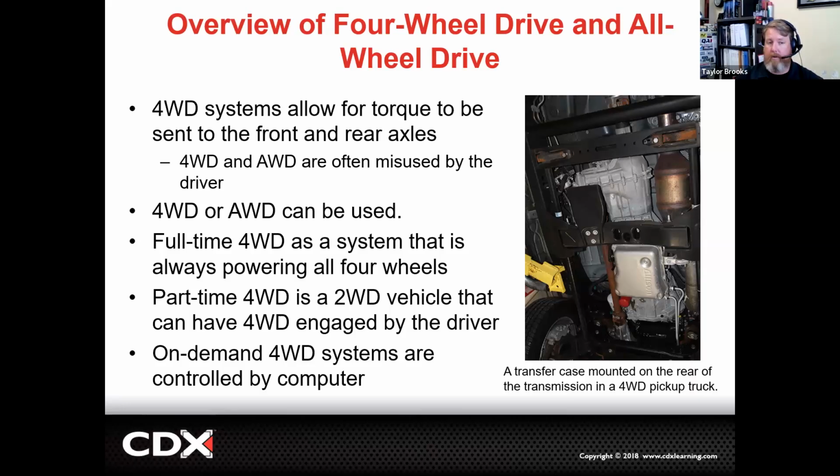Part-time four-wheel drive is what probably most of you are familiar with seeing in Jeeps and off-road vehicles. Part-time four-wheel drive indicates that part of the time you can drive the vehicle in two-wheel drive, or you can select it to drive in four-wheel drive, depending on the road conditions. In most driving applications, in fact, about 98% of the time, the vehicle is going to be driven in two-wheel drive or just rear-wheel drive mode only. And then when we select four-wheel drive, either high or low, it will then send torque to the front wheels.